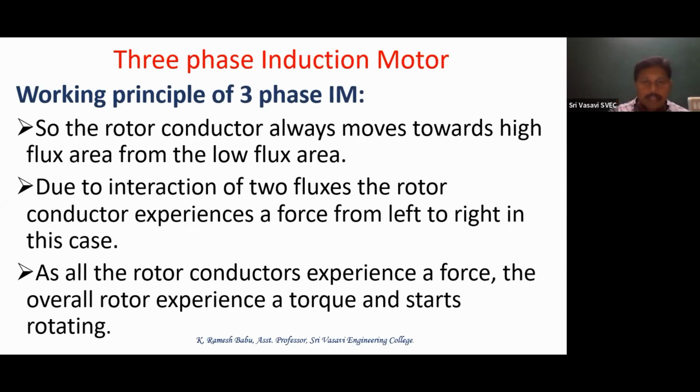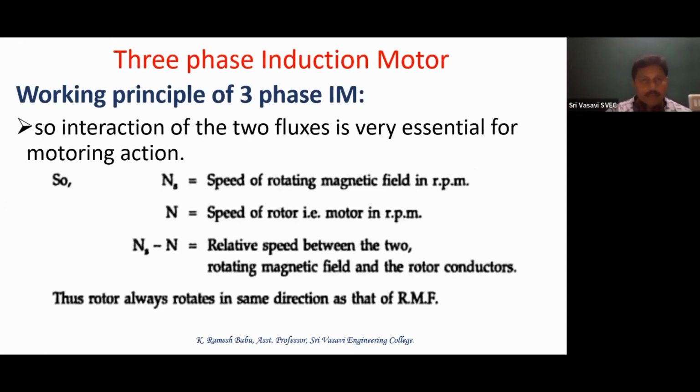So all the rotor conductors experience a force. The overall rotor conductors experience a torque and start rotating. The interaction of these two fluxes, that is the rotating magnetic field and the flux due to the rotor current flowing in the rotor conductor, is very, very essential for motoring action.